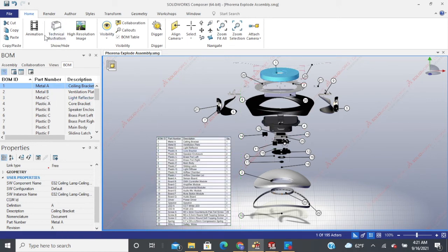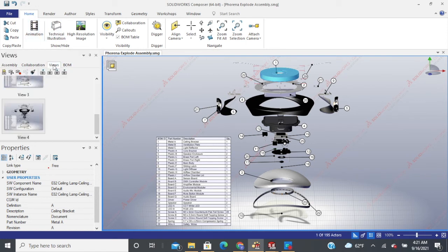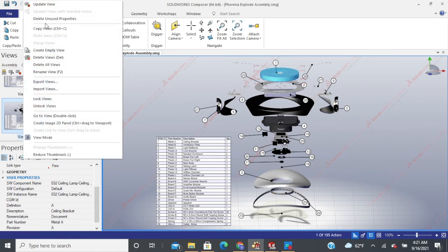So yeah, and in here you can make an animation with different cameras based on the view. So here I have different views of the property I made. It's also active save point. So you right click, and you click on this, it will allow you to save, create a new view, and then take a camera view in any direction without creating a new view. And this is update the old view. Go to right click and it will show you all the options.